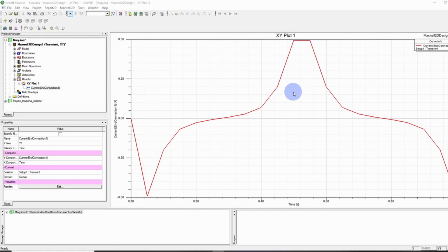And the idea here is that we have the derivative of the flux to be 0 around 35 seconds and around 75 seconds as well. And this is happening in the position in which is around the angle of 19 degrees, in which you have the magnetic flux to be 0 due to the cosine of the angle between those coils and the magnet to be 0.